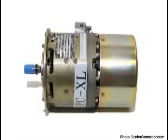When lines of magnetic force are cut by a conductor passing through them, voltage is induced in the conductor. The strength of the induced voltage is dependent upon the speed of the conductor and the strength of the magnetic field. If the ends of the conductor are connected to form a complete circuit, current is induced in the circuit. Figure 9:1, inducing maximum voltage in an elementary generator. Figure 9:2, inducing minimum voltage in an elementary generator. Figure 9:4, inducing a minimum voltage in the opposite direction.